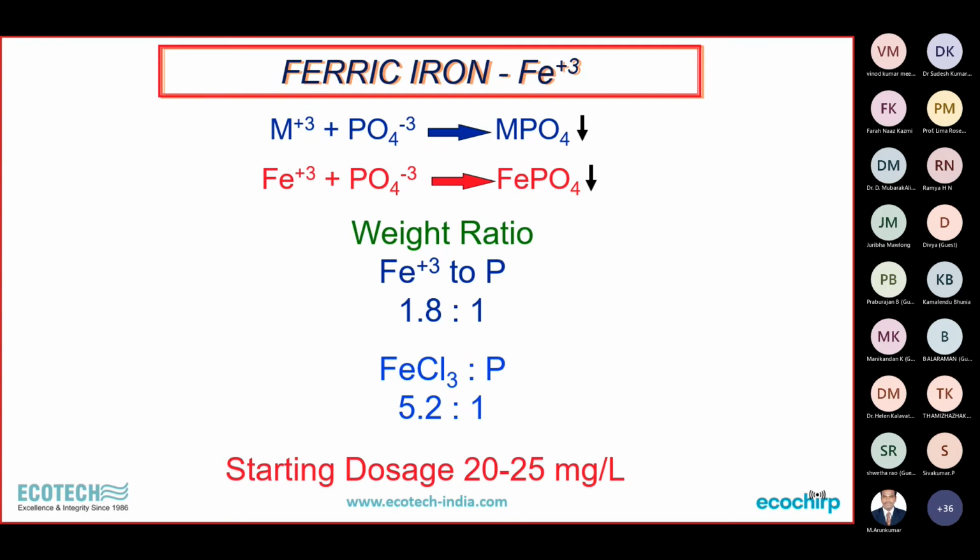But you could fine tune this later based on your actual experience, specific treatment plant site. As I said, it can be different. Phosphorus content also may be different depending on whether it's a residential complex or whether it's a mall or a hotel. So we have to actually study the phosphorus concentration, understand the phosphorus limitation and the limits to which it has to be treated.